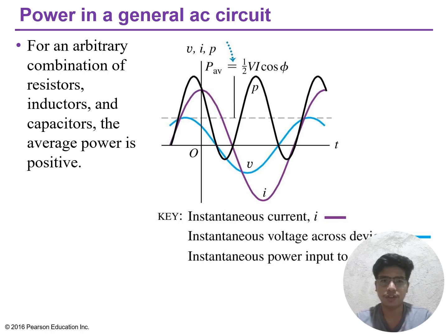So the average power using the RMS values is V_RMS times I_RMS times cosine phi. This is universal for AC circuits. So this explains why utilities penalize low power factor circuits, showing the same current but with poor power factor consumes more power from generators without doing useful work.